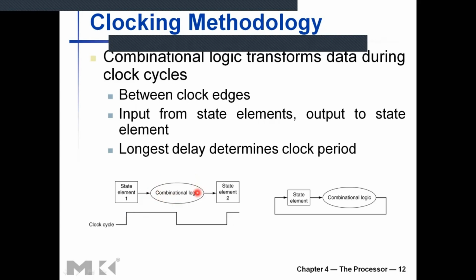It will take some time. For example, you read from the register file, which is a state element, you perform some operations, and you write into the register file, also a sequential element. So you can read and write at that clock edge, this rising edge here. But between the two rising edges, your combinational logic needs to complete the given operation.